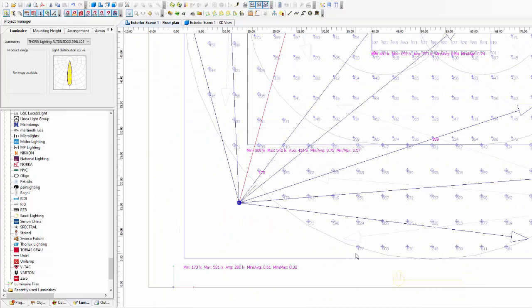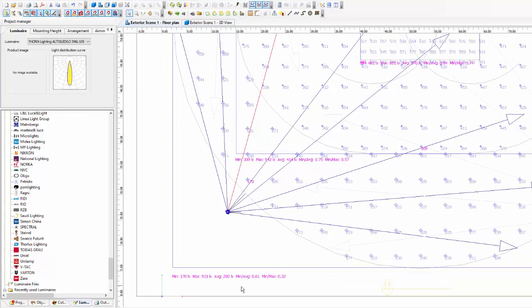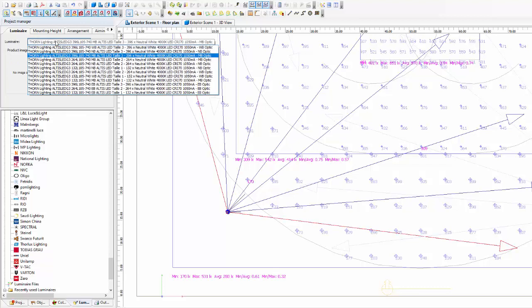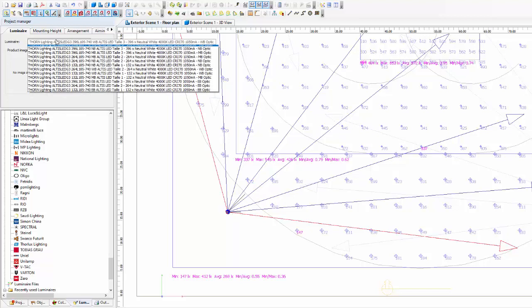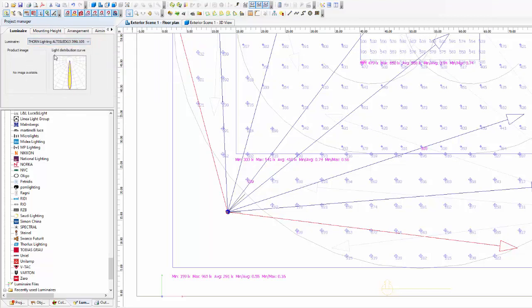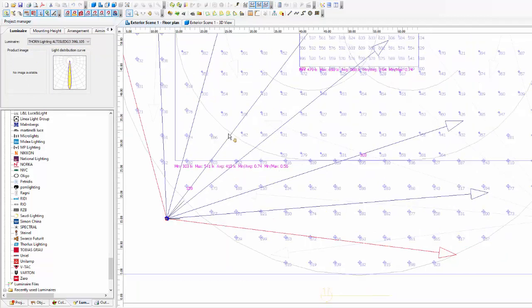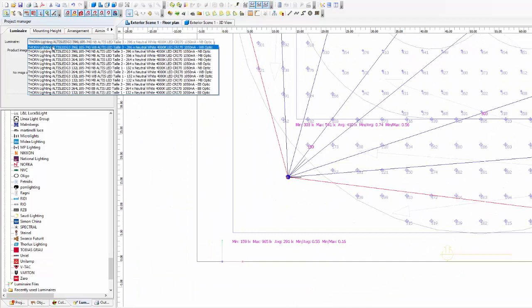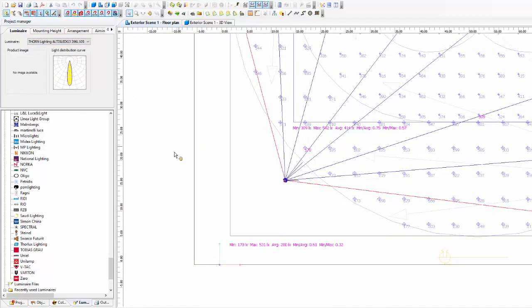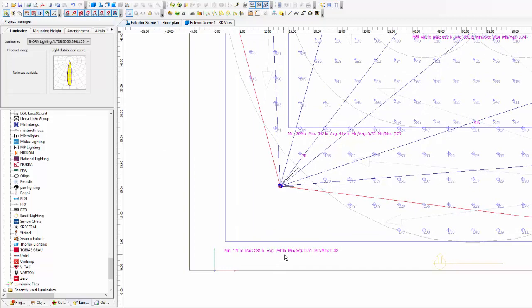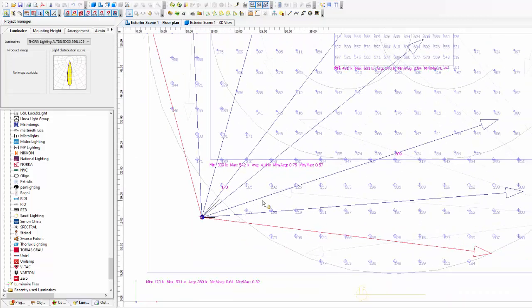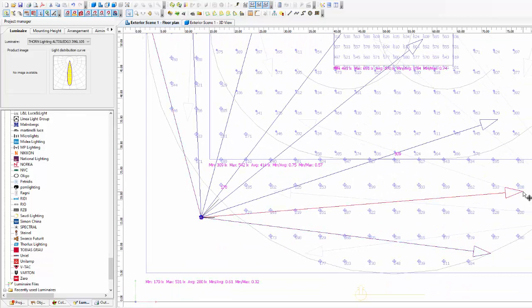All right, so I save it now, and then let me have another 280 lux. What if I change this one into wide beam? No, medium beam, narrow beam. Yes, it's okay, but the overall uniformity suffers. Okay, so let's just work on the 20 lux. Okay, it's just a 20 lux, and we need to work on it.